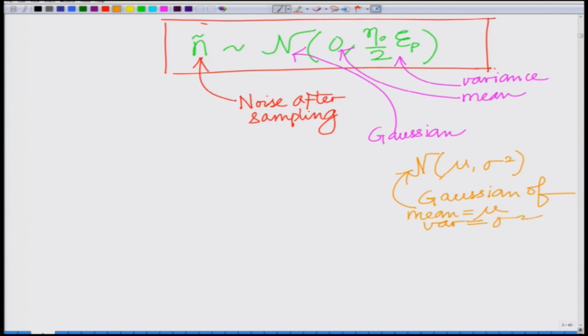So, we have our noise n tilde. Remember, the argument went as follows: n t, the noise, additive white Gaussian noise, is passed through a linear filter, that is h t. Hence, the output noise process n tilde t is also Gaussian, and when we sample it, the sample of a Gaussian random noise process is a Gaussian random variable. Therefore, n tilde is a Gaussian random variable.